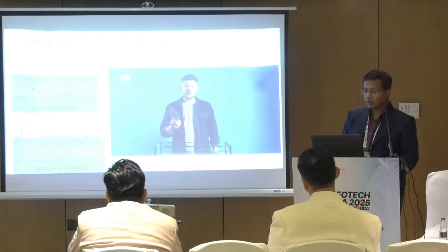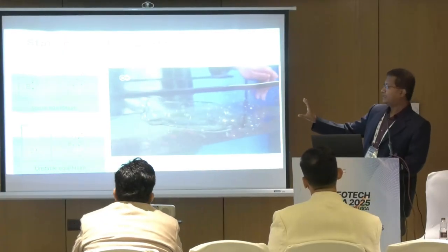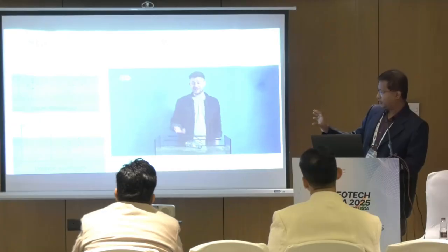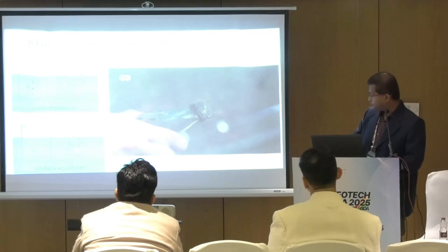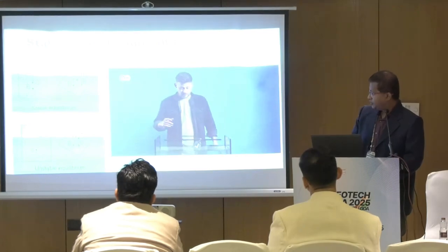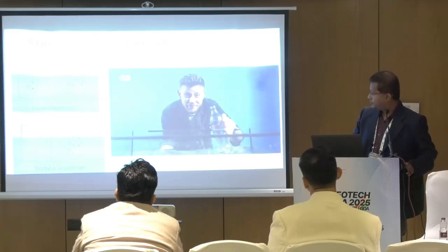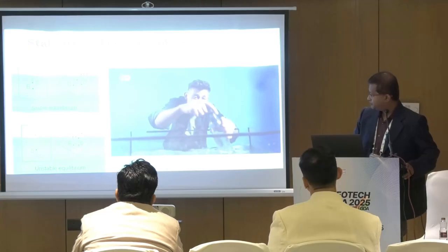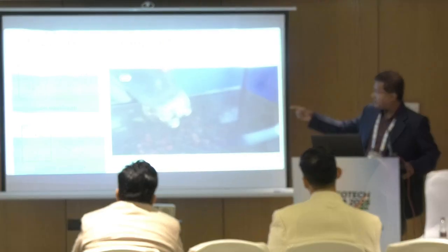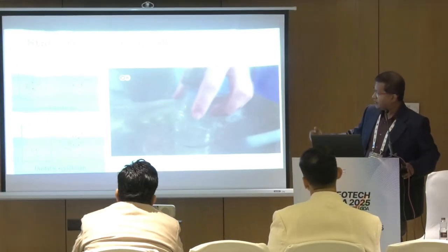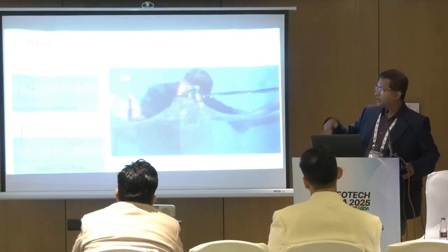If you look at this small interesting video, you can see how the spar type of foundation is balanced using this kind of philosophy. It's getting a bit more stable, but not super stable. Now when you add something heavier, like these stones, it is just like a ballast. Considering this ballast, the center of gravity is much lower, so that it will give more stability.